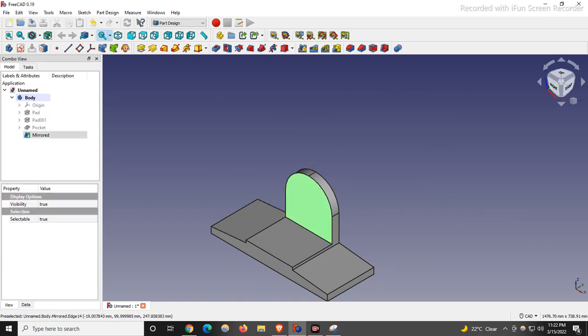The hole diameter is 100 mm, so you do not need to use the hole feature. You can use the cut, because this type of larger hole is made by milling. If a blind hole has a diameter of 12, 15, 25, it is possible to do with drilling, but for a larger hole you can use the cut feature.